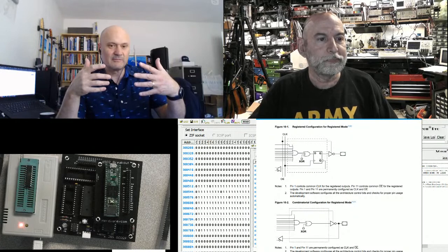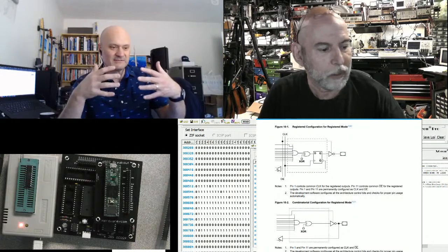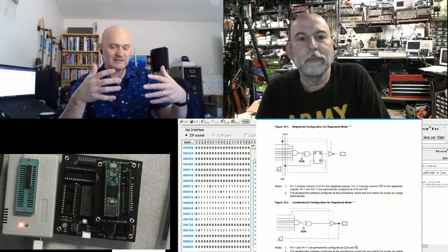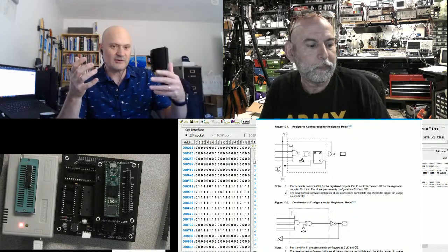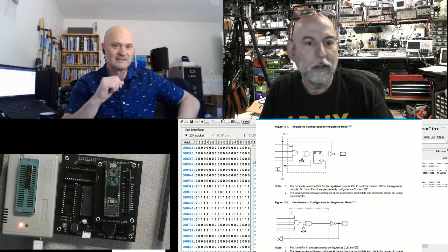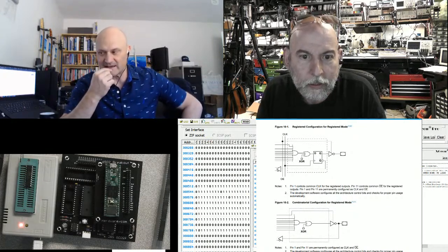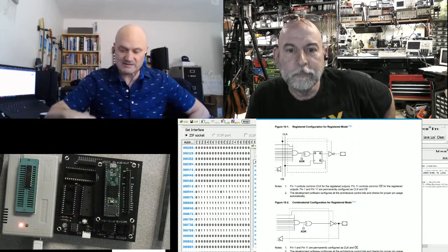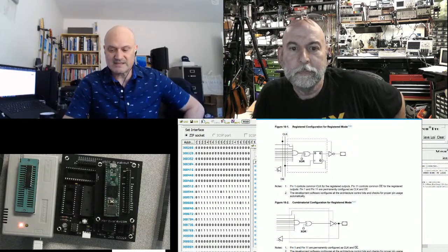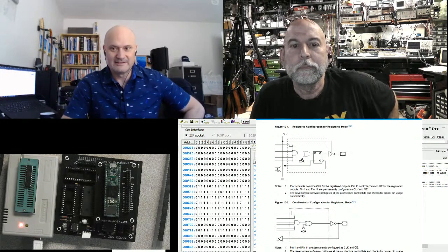It's configurable, and while it's powered up, it retains the bit pattern inside, and then the outputs depend on the address input to that RAM cell. So they're fundamentally different in how they operate. They use a lot more power, tons more power, because the static RAM uses a lot of power, right?